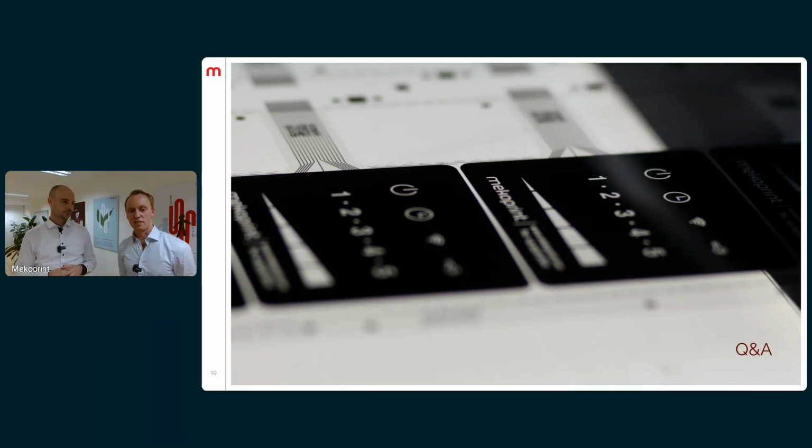So first of all, you have the thickness of your substrate. This will usually be 125 or 250 microns thick. And then the thickness of the individually printed layers is usually a few to 10 microns each. Then you add an adhesive, and then you'd often be maybe around 250 microns in total on a thinner substrate. But yeah, it also depends a lot on the printer and whether you need a dielectric layer and whether you need an adhesive in your sensor.